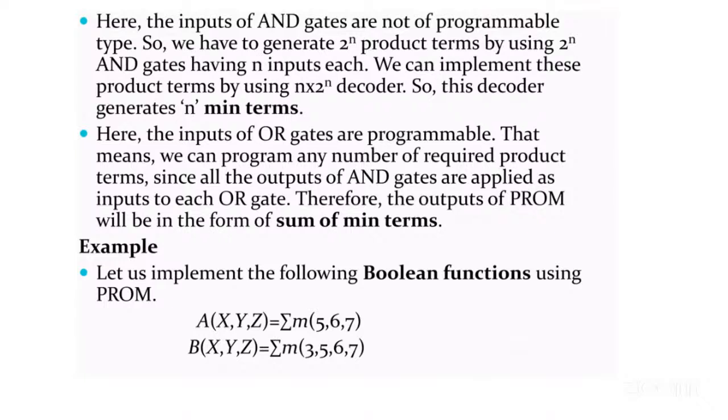Here, the inputs of the OR gates are programmable. That means we can program any number of required product terms. Since all the outputs of the AND gates are applied as inputs to each OR gate, the outputs of PROM will be in the form of sum of minterms.